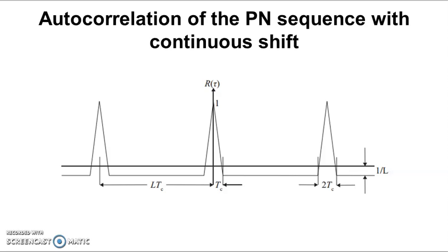In that case, we need to find out what the clock rate and the phase will be. If the phases of both sequences match in the matched filter, it produces a high output, at which instant the clock frequency is locked to the frequency of the received PN modulated data.